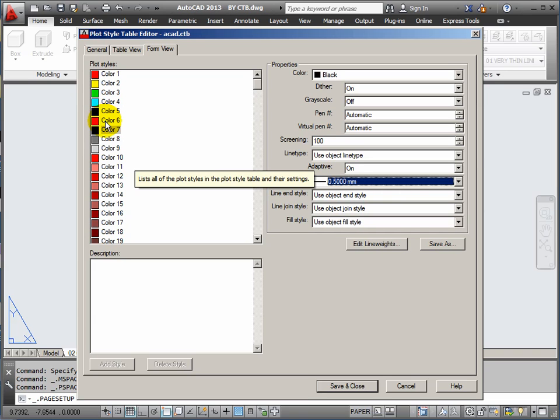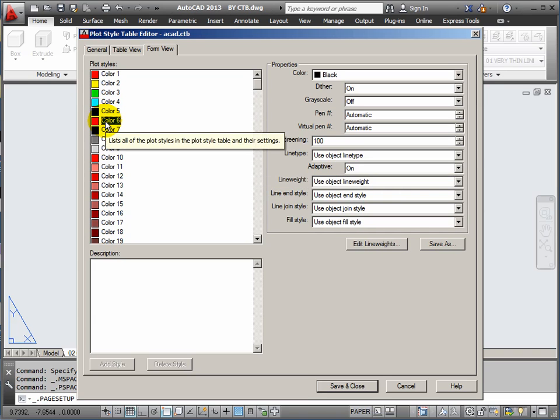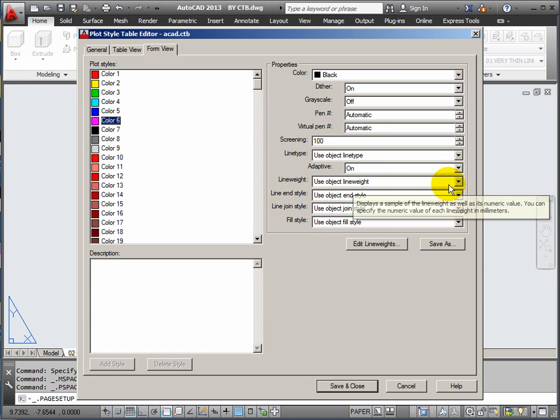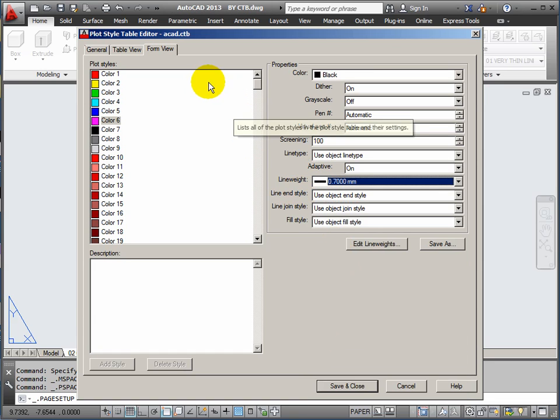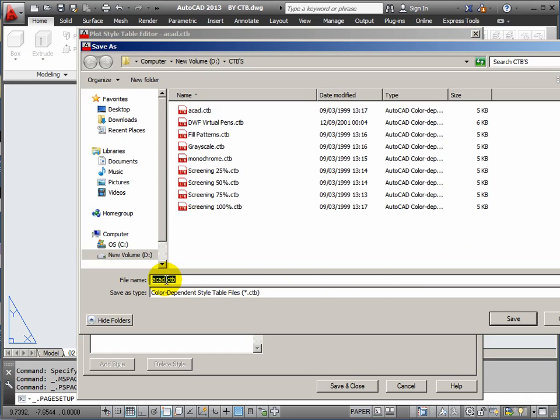And then my final one, my very thick line, was magenta coloured because it's a horrible colour, and I'm going to use, let's say, 0.7 for that. Okay, so I've made those changes, and I now want to make it mine, so I can do save as. What I tend to use is a little phrase, black and colour, because it allows me to have black pens and lots of other colour pens. I'm just going to make that lowercase.